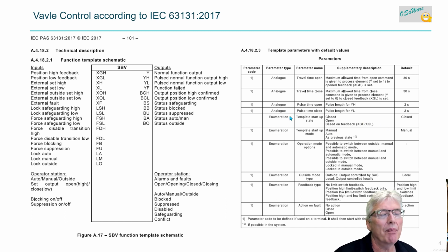Starter mode, which means that you restart your PLC or an instance is loaded fresh onto your PLC. So it should start up in closed, open state or based on feedback. The sensible thing to do is usually based on feedback. But okay, default is it should start up and go to closed if it's open, and so on. There are some other options too here. Well, that was it.